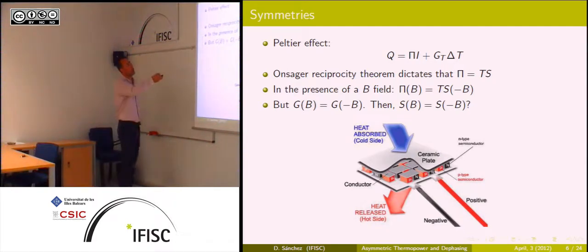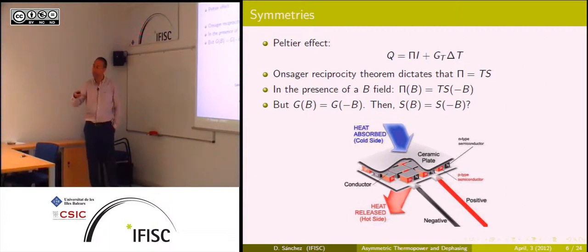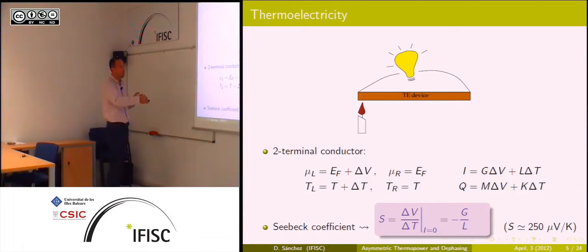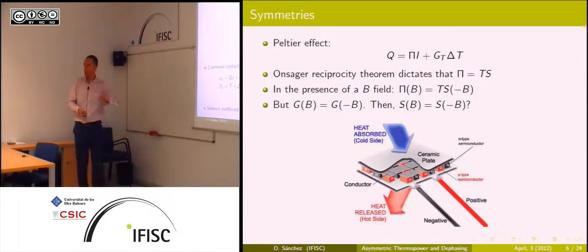Because now you can do a similar experiment, but instead of looking at the electric charge, you look at the energy charge or the heat flux. Then you can put here, for instance, a 0, and then you can drive a current like in these kinds of devices, so that you can actually pump or absorb heat. In this way, the Peltier effect, which is a kind of cooling or heating effect, is really connected to this thermoelectric generation.